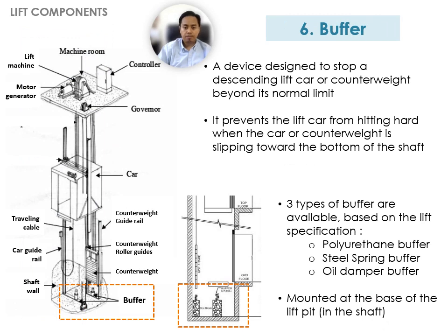Next is the lift buffer. What is a lift buffer? It's a device designed to stop a descending lift car or counterweight beyond its normal limit. It prevents the lift car from hitting hard when the car or counterweight is slipping towards the bottom of the shaft.